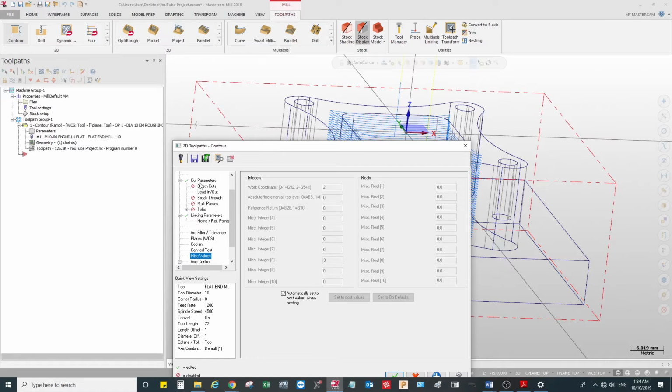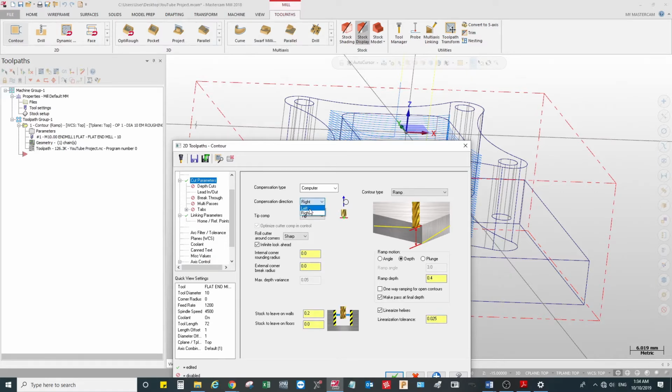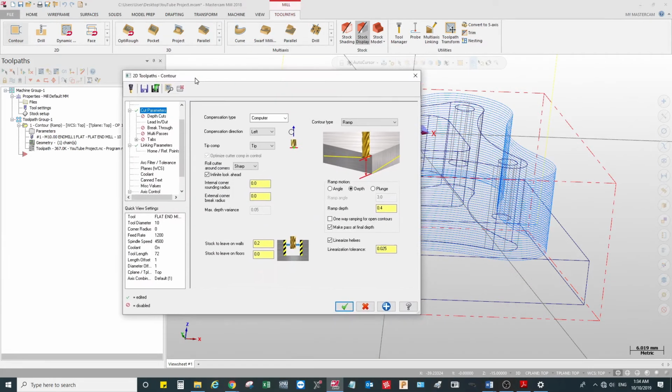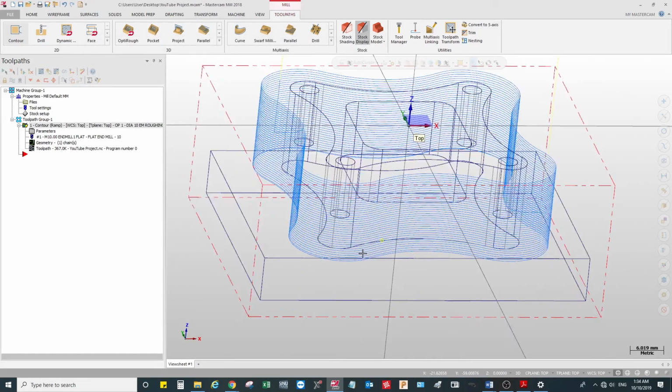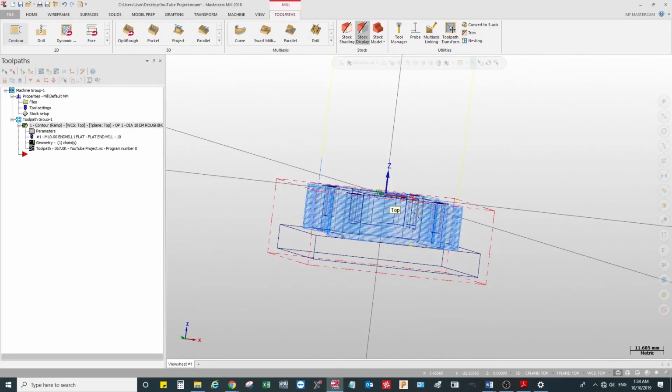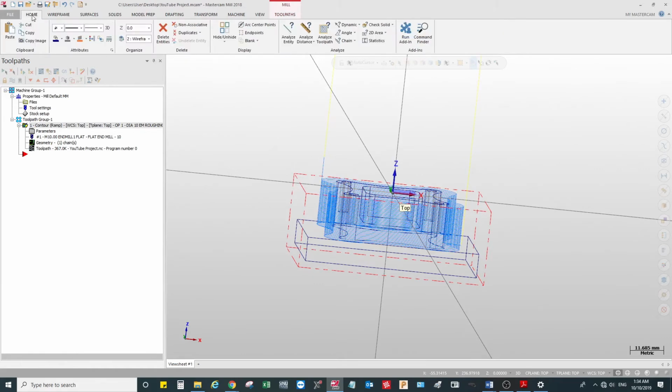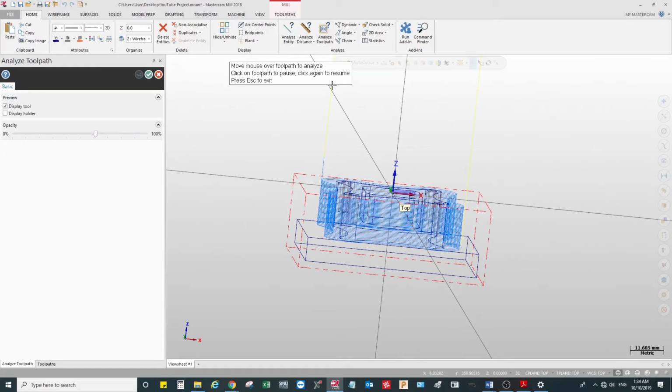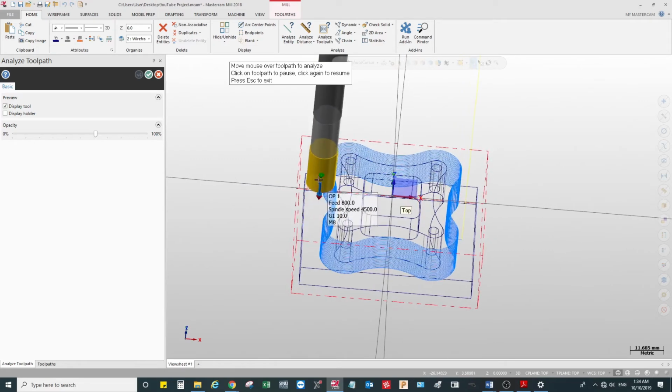So you just need to be really careful. I use 100 millimeter as the clearance, and I use clearance only at the start and at the end of the operation, and I keep the clearance absolute. With the retract, I just want to keep it a little bit safe, so I give 25 millimeter and click on absolute. With the feed plane as well, where the machining starts, I give 10 millimeter, and I usually use an incremental value for that. It's much better, it saves time.